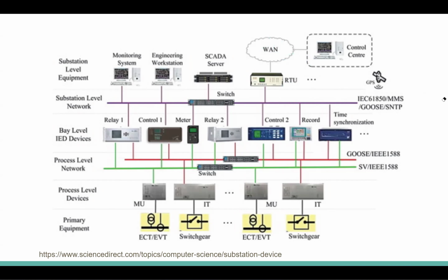Okay, there we go. This is a diagram that I liked, where it really shows the overall communication layout that you would see in a substation. A lot of the things we just talked about show up here. For example, we have an RTU, which is basically a real-time controller. It's acting as our gateway and doing protocol translation. We have these different protocols listed here, like 61850 GOOSE, MMS. We might also have DNP3 here, but then the control center that's off-site is speaking some other protocol, and so this is going to do a translation between those protocols.